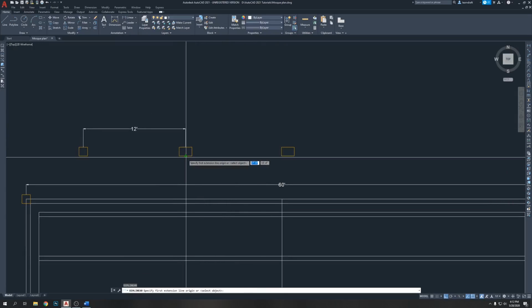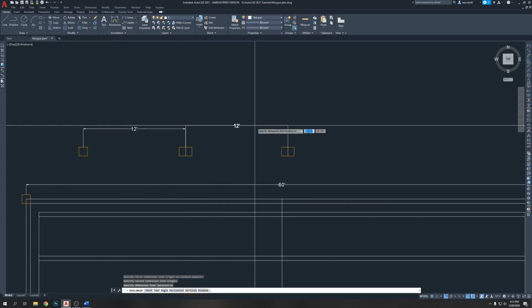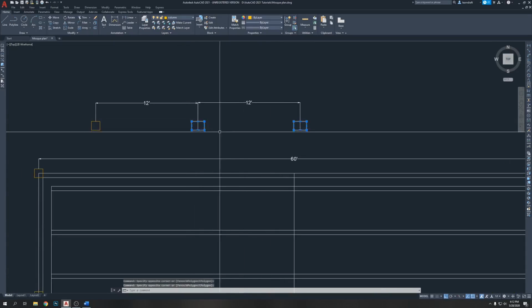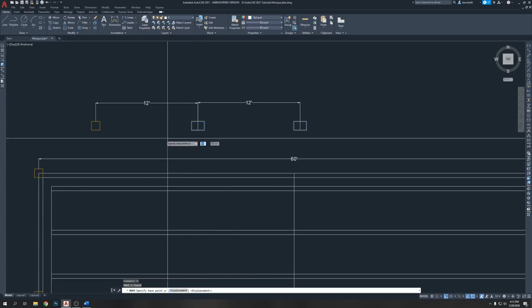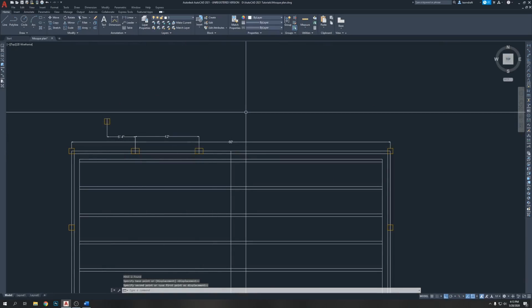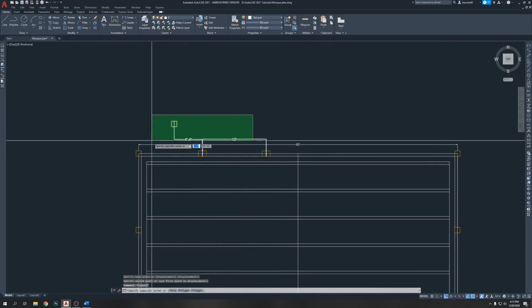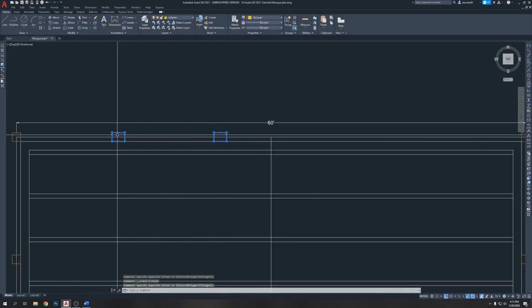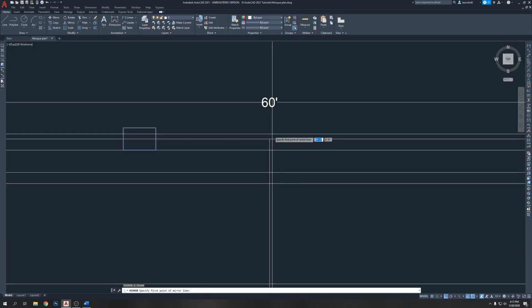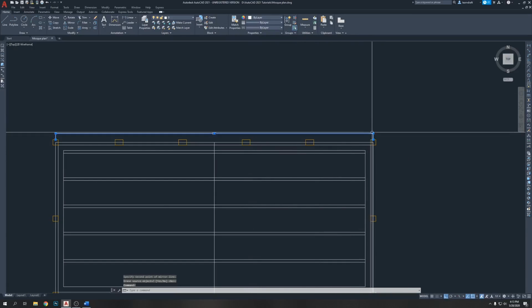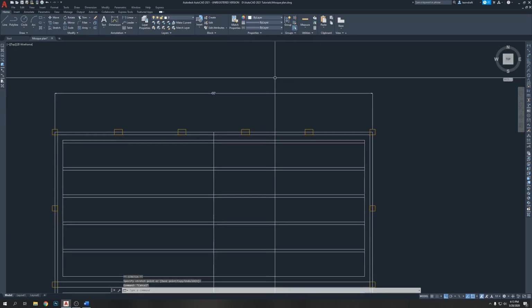Hopefully the 18-inch moved along. Good. Now we're gonna bring this to M, enter. Select this outline so you can place on this outline, and it's set. Let's delete these things so it's clear, and then we're gonna mirror this to MI, enter. Center line, click, enter.